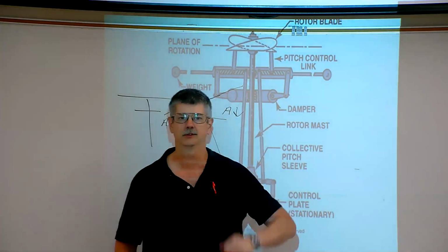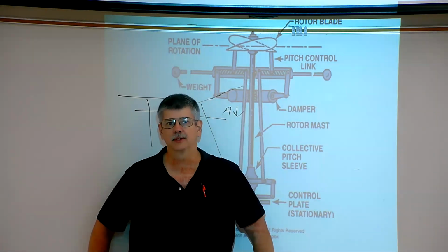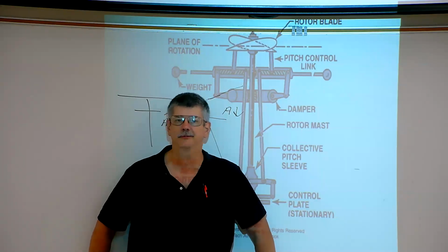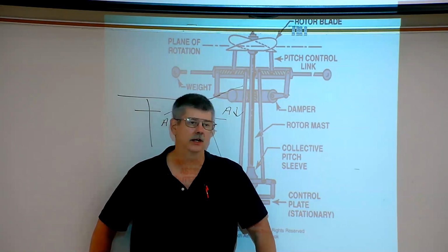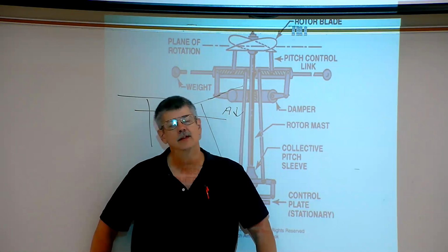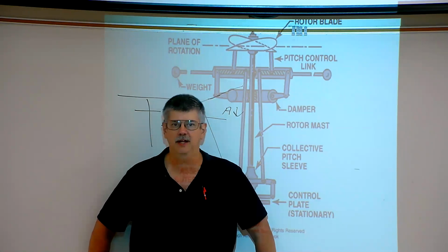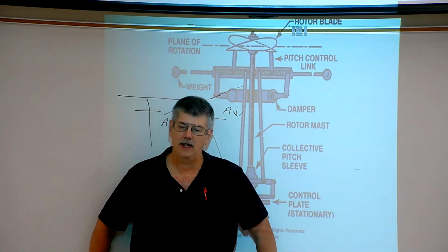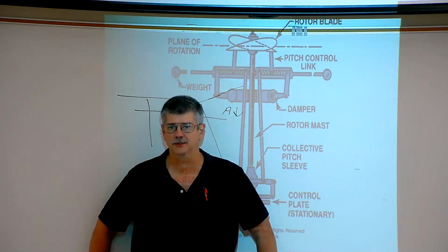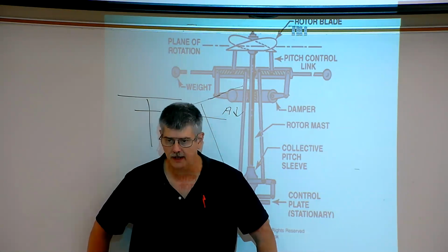So if you ever become a mechanic on helicopters and a pilot comes up to you and says, hey, I'm feeling vibrations, you could say, okay, well, is it a high frequency vibration, like a buzzing that you feel? Or is it more of a thumping, boom, boom, boom? Oh, it's a high frequency. Oh, okay, now you can start looking at the tail rotor and drive shaft for the tail rotor. That would most likely be the cause. Whereas if it was a low frequency, then you would start looking into the main rotor system, okay?